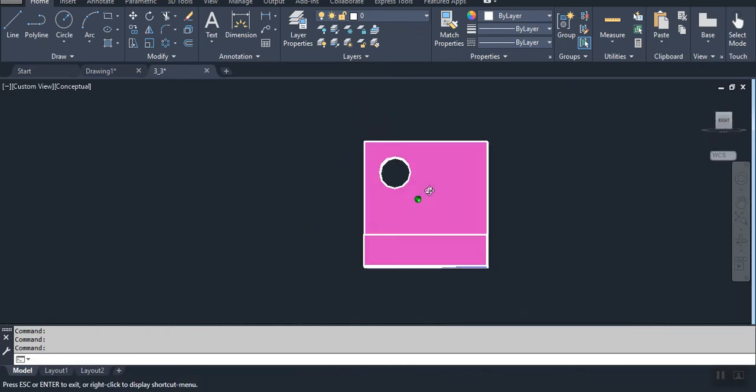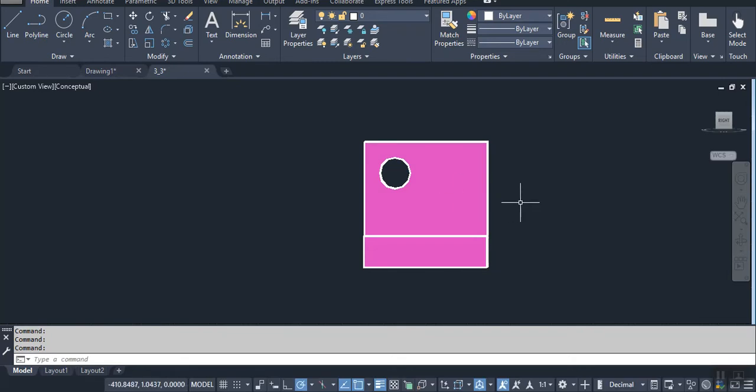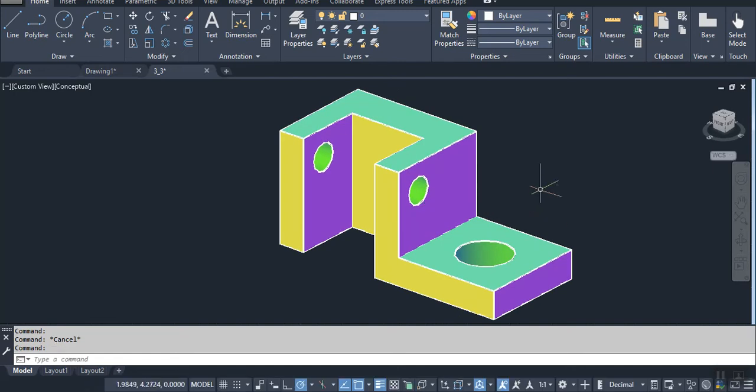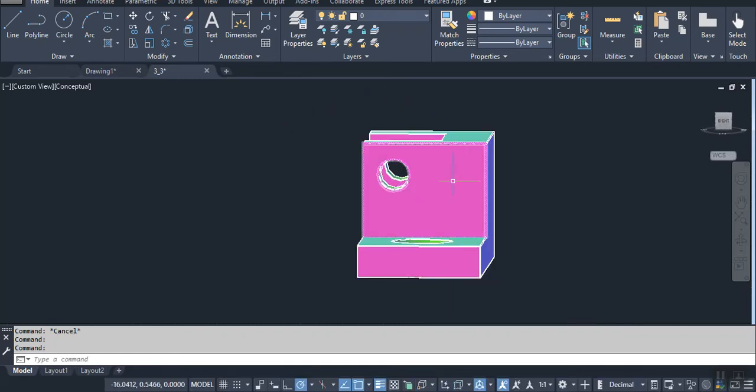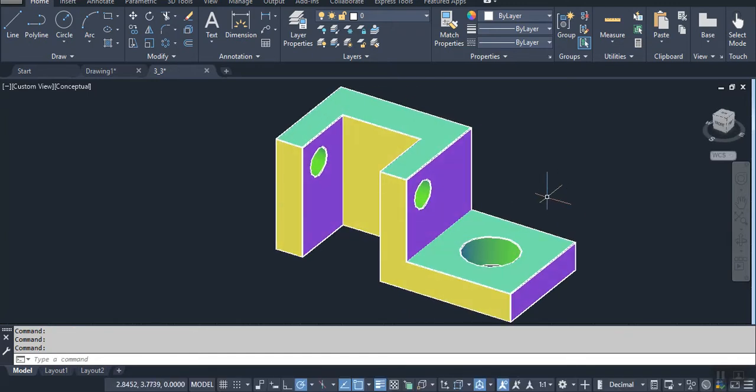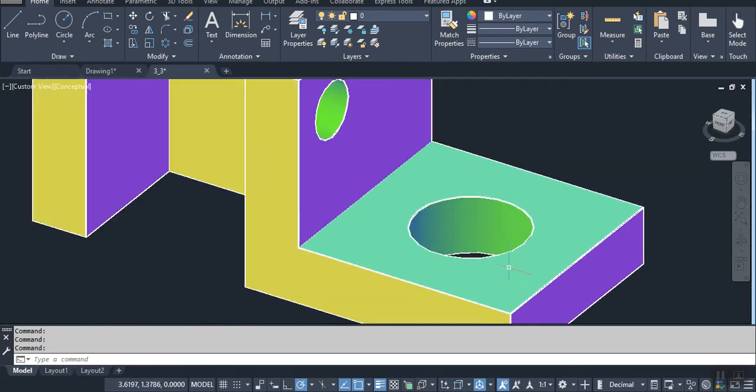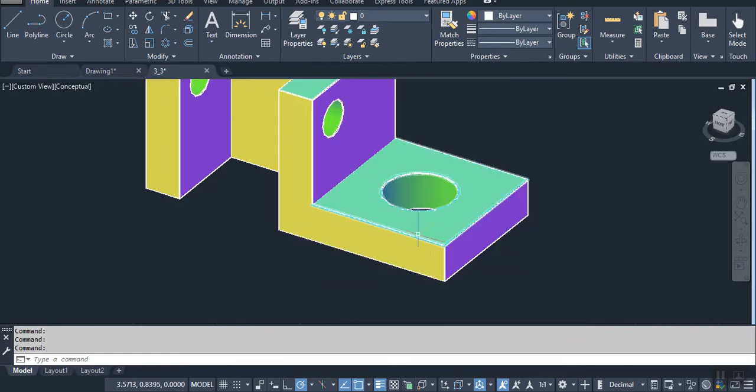And then thirdly, we would spin around to the side there and get a pretty clear view of the surfaces that we're working with as well as the edges. You can probably see that I've color coded this. Yellow surfaces are front planes, cyan surfaces are top planes, the magenta surfaces are right side planes. And for things with angles, I've tried to use a contrasting color, and I've also used a contrasting color for curves, because curves obviously can exist in two planes at once. If I rounded off this corner, you'd see it from the front and from the side, so it's got its own color.